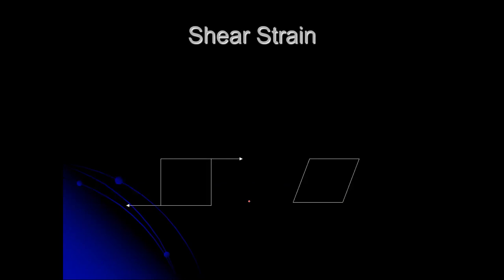Now, I did mention that shear strain is a thing, but it's not something we tend to worry too much about, primarily because shear strain is hard to measure. But if you've ever tried to build anything like a frame or a box or a house wall, and you've applied a side load when you really didn't intend to, and the whole thing just kind of slid to one side or the other, and all the angles went from 90 degrees to something else, you've dealt with shear strain. But shear strain is about deformation in angle, not necessarily in length. And so it's a lot harder to really be useful in that sense.